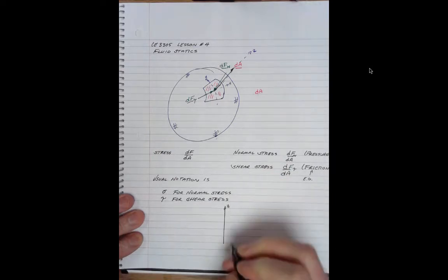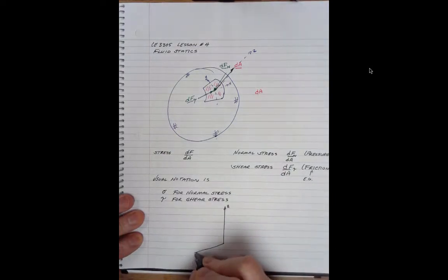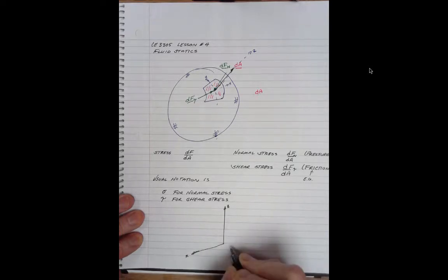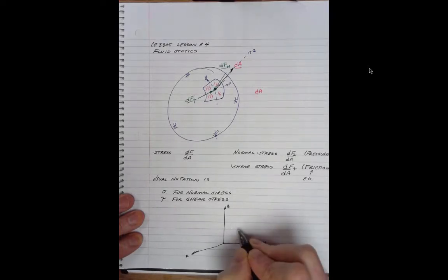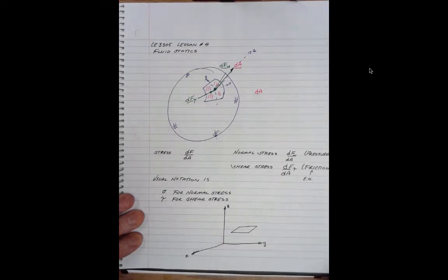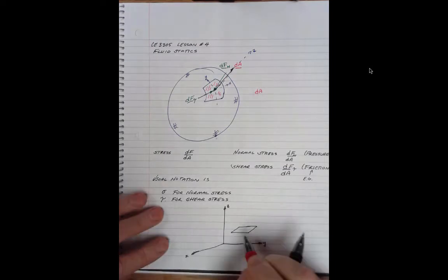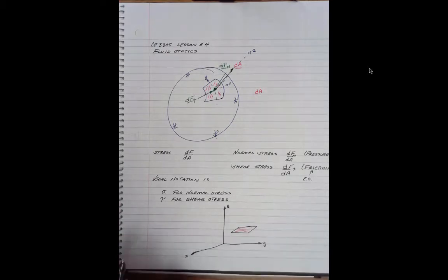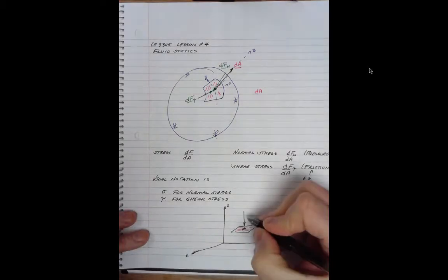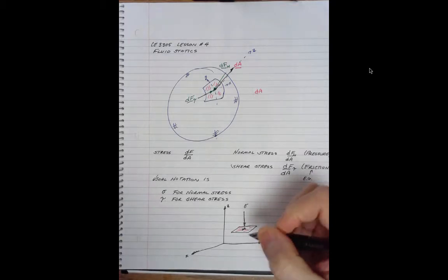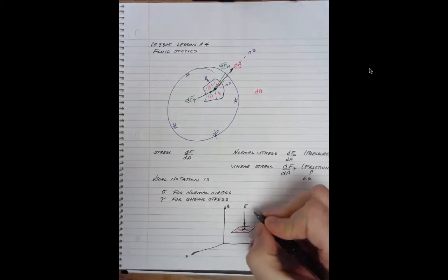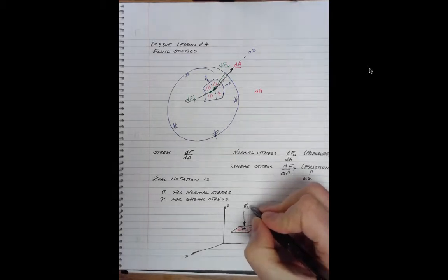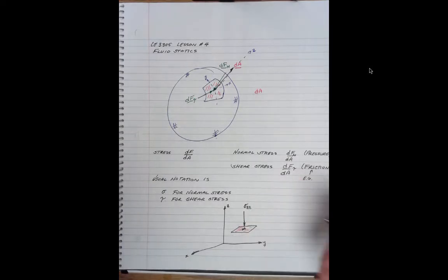So here's our z-axis again. Here's our x coming out to get you. And y-axis. And we'll just put a plane out here like that. And I'll go ahead and color it with red to remind us of our area of interest. So here's our normal stress, at least on that plane, and that would, in 3 dimensions, be double subscripted, in this case with zz.